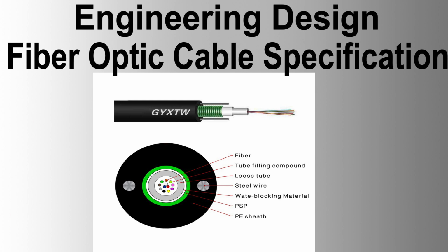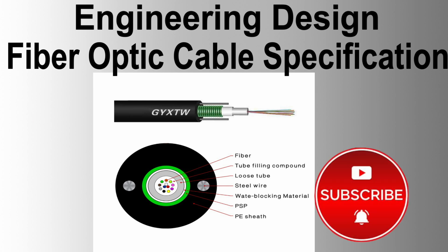Tests to include optical fiber cable attenuation per kilometer, splice attenuation, acceptable test result data, fusion splice attenuation 0.1 dB. For the whole cable loop, including connectors at both ends, 90% of splices shall show an attenuation of less than 0.15 dB. FO test instruments: optical time domain reflectometers, calibrated laser source and power meters, appropriately fitted connectors ready for use. OTDR selection, based on fiber optic specifications and requirements, with considerations for dynamic range, resolution, minimum operating distance. A calibration test certificate not older than 1 year for the OTDR and power meter.